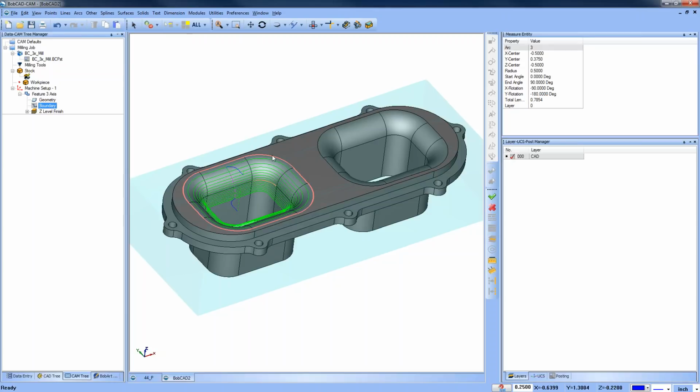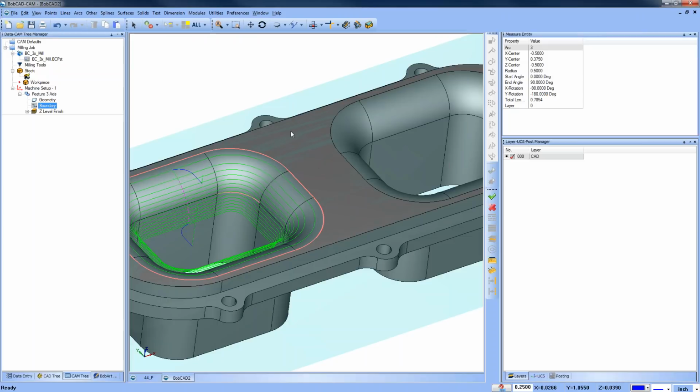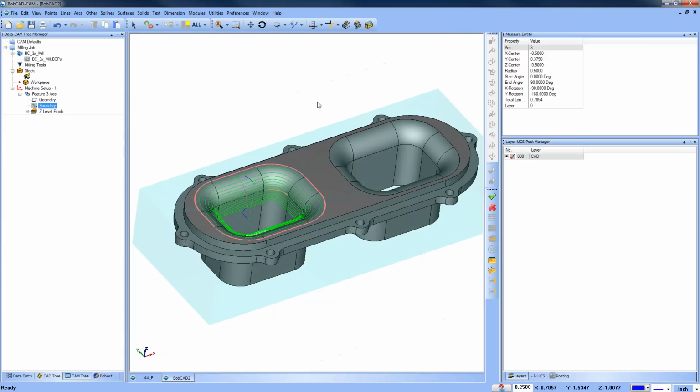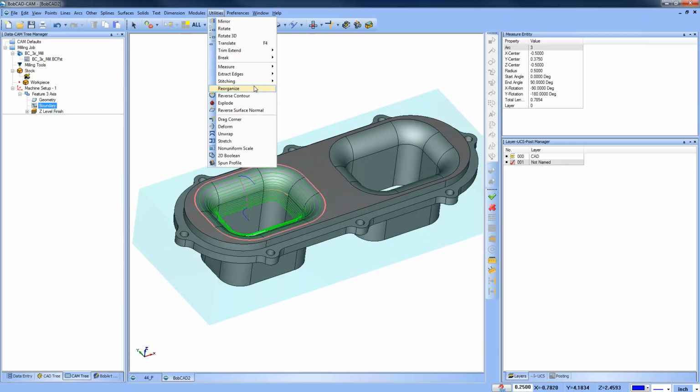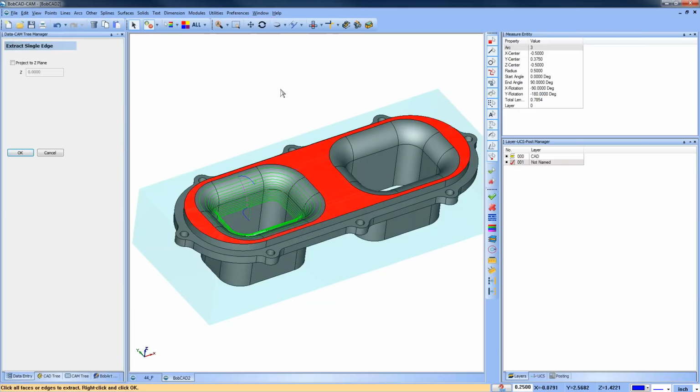We could offset our boundary. We could extend our boundary out further, but the issue is this surface is shallow. It's flat, and as the radius here, see what he's talking about is getting more passes to go past this edge here. So if we offset our boundary here, is it going to get us more passes? I'm not sure. I don't think it will, but let's find out. So we'll do this real quick. We're going to extract edges for this face.